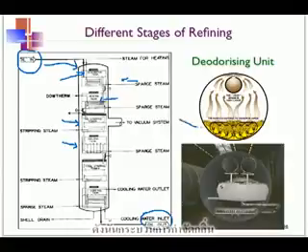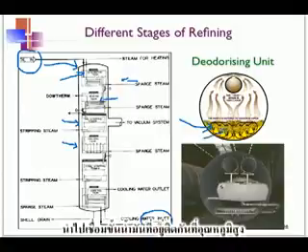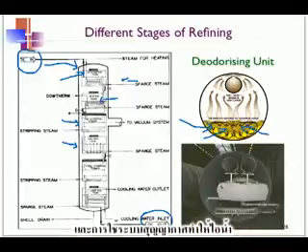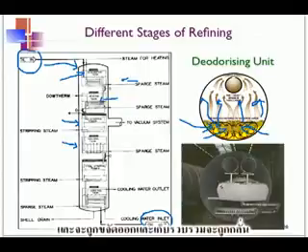So during this process, the steam will be sparged into the deodorizer unit and will come into intimate contact with the oil, and the high temperature and the vacuum condition will allow the volatiles to vaporize into the large headspace vacuum space here, and will be removed and collected as distillate.